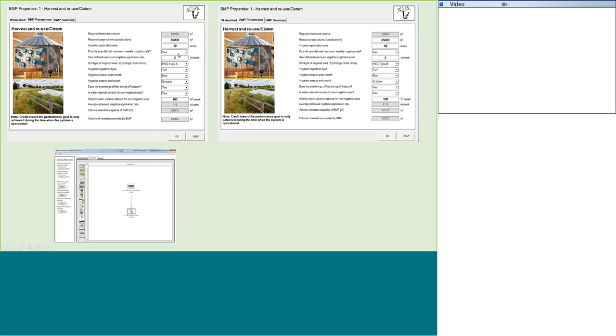In that case, it would just take your potential evapotranspiration and use that to calculate your volume. So on an A soil, I can put in 2 inches in a week, and it's going to take all of that water. If I did that on a B soil, it's going to default back to either your irrigation rate or the PET, whichever is the smaller of those 2 values.